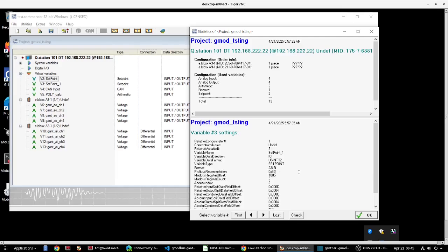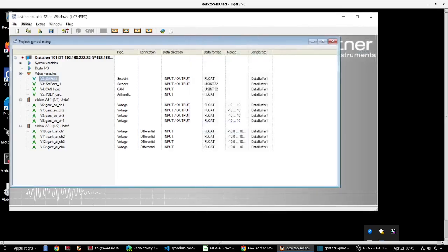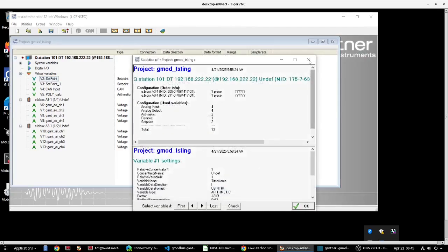It's important. If you've used a lot of gmodbus in your life, you probably already know this, but you're going to have to offset this by 1. So this set point 1 is actually register 1006. I used modpoll myself to figure that out because I find that that's a much quicker tool than restarting gmodbus a bunch of times. And then this variable, you're going to see there's an arithmetic calculation. And so this would be register 1010. Again, that button's right here to get those registers.